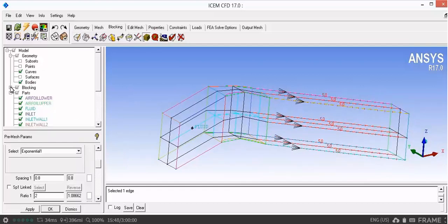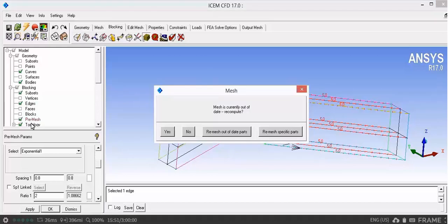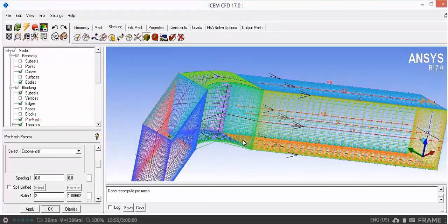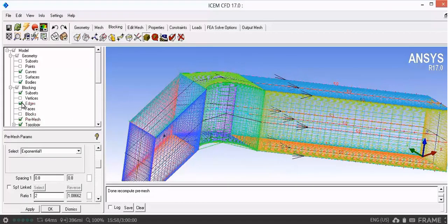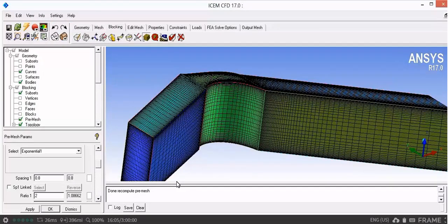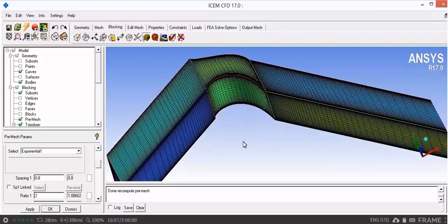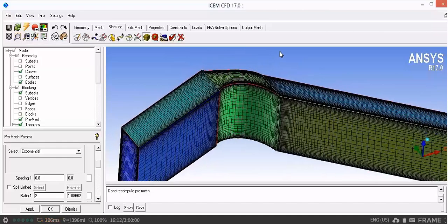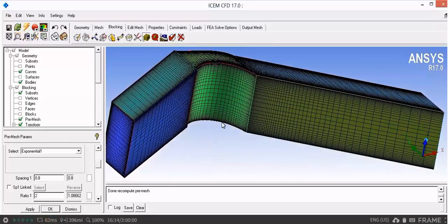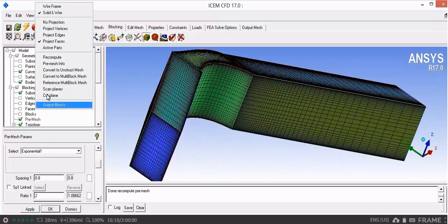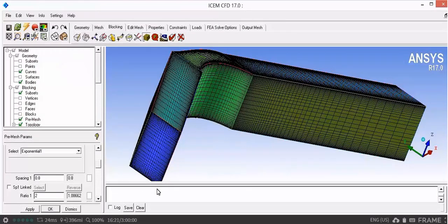After finishing with sizing, we can compute the surface mesh. The solid option gives us better visibility of the mesh, therefore we can activate it here. We can also check the number of nodes of the volume mesh we just created.